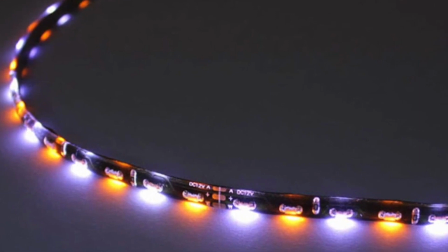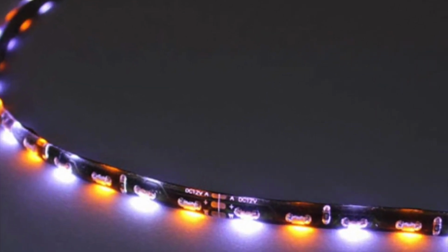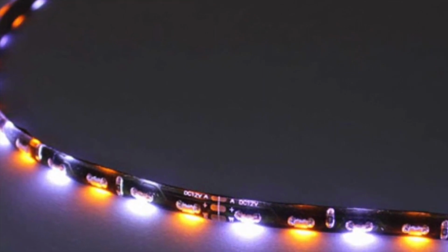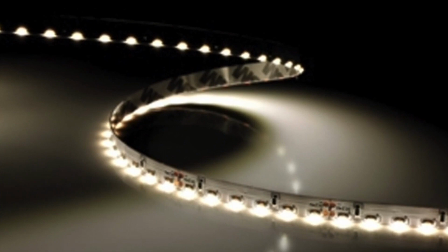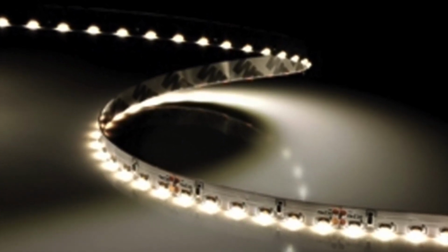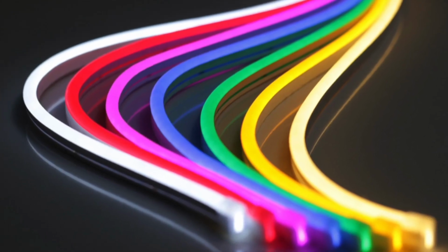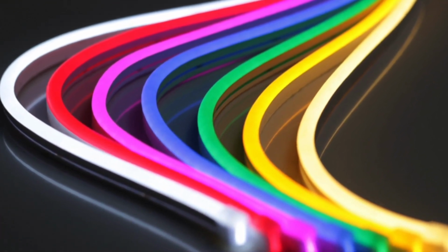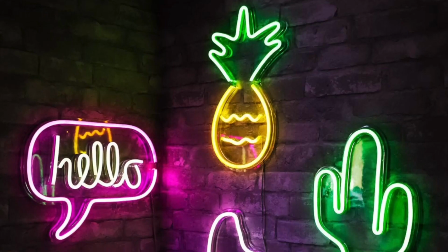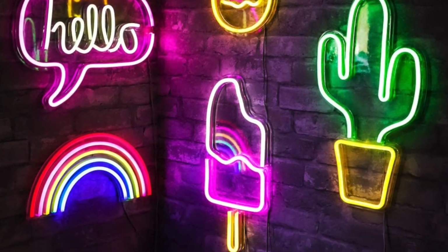Side-emitting LED strip. These are powerful when you want to use LED strips, but you need to attach the lights to the inside of a solid shape, such as a tube or half dome, or need them to shine out rather than up. Unlike regular flat strips, these strips can bend to an extent without damage. LED neon. These LEDs are embedded inside a thick neon look diffuser. They're quite flexible, making them perfect for lining complex surfaces, using as recessed lighting in a room, or making neon art.